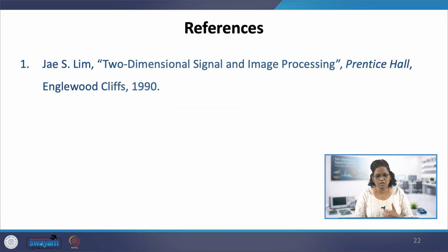There are two steps, one is row-wise and the other is column-wise. Unless we know the 1D DFT and extend it to 2D DFT row-wise and column-wise, which is very helpful, otherwise you have to go for 2D direct computation using the formula, which has more computational complexity compared to row-wise and column-wise DFT.